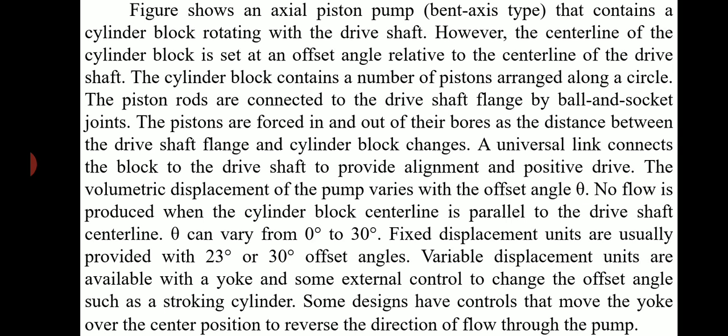The volumetric displacement of the pump varies with the offset angle theta. No flow is produced when the cylinder block center line is parallel to the drive shaft center line. Theta can vary from 0 degrees to 30 degrees. Fixed displacement units are usually provided with 23 degree or 30 degree offset angles.